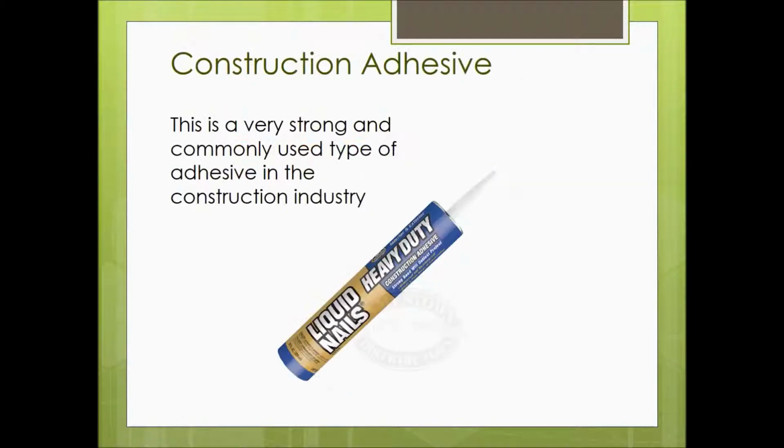Okay, construction adhesive is sometimes called liquid nails. This is some pretty strong stuff. It's used a lot of times when you're building floor systems to glue the plywood down to the floor systems. So that's some pretty stout product right there.